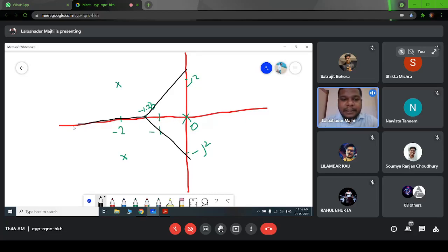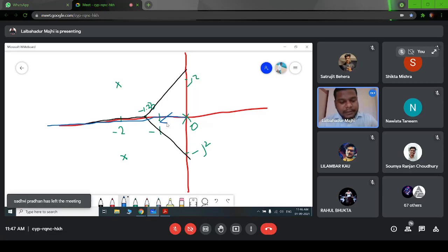Because for any point on this real axis, towards its right there is only one pole. So this whole path will lie on the root locus, and this root locus will follow the 180-degree asymptote. So this will be our first root locus branch. Okay, the direction will be on this side, and this root locus will follow the 180-degree asymptote, right?